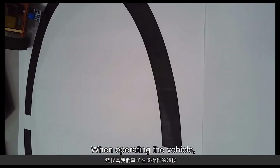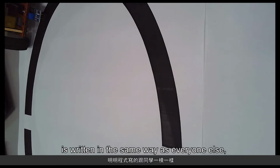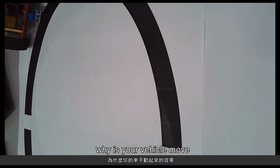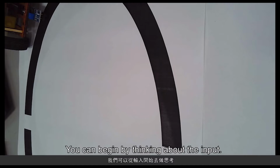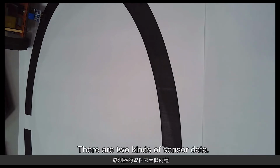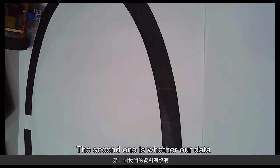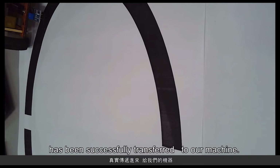When operating the vehicle, even though the program is written in the same way as everyone else, why does your vehicle move differently from others? We can think of some of the problems. You can begin by thinking about the input. The first one is whether the sensor data we are sending is correct. There are two kinds of sensor data. The first one is whether there are issues with the hardware. The second one is whether our data has been successfully transferred to our machine.